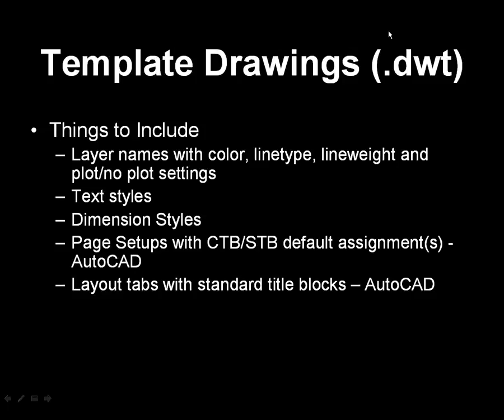And I put in here that this is for AutoCAD. Right now, IntelliCAD does not have page setups that can really be defined. And at the end of this, we're going to take some questions for the last 10 to 15 minutes. I may be a little bit wrong on that, but primarily when we think of page setups, we're going to be talking about AutoCAD. The CTB files and STBs, for those of you that know or that don't know, can be applied and are applied in IntelliCAD just like they are in AutoCAD. The page setups is kind of the difference here between AutoCAD and IntelliCAD.